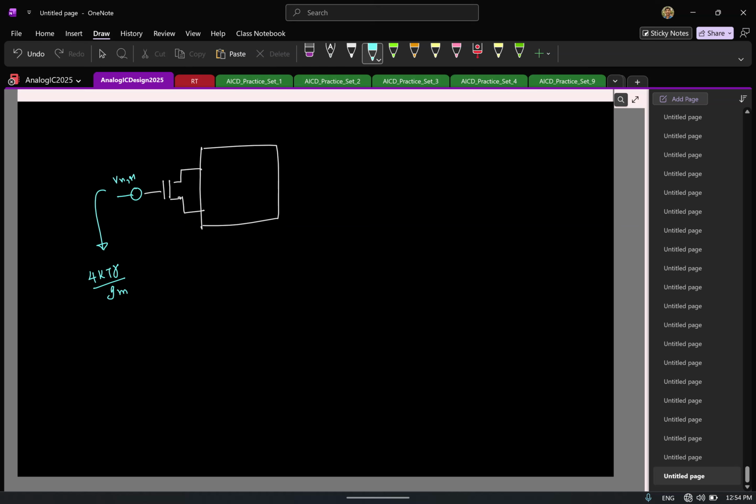And this is a nice thing because in all our circuits, input is given to the gate of a MOSFET. Which means for those transistors, we don't have to go and compute the noise contribution. You can straight away write that the input MOSFET directly adds to the noise. Is this statement fine?